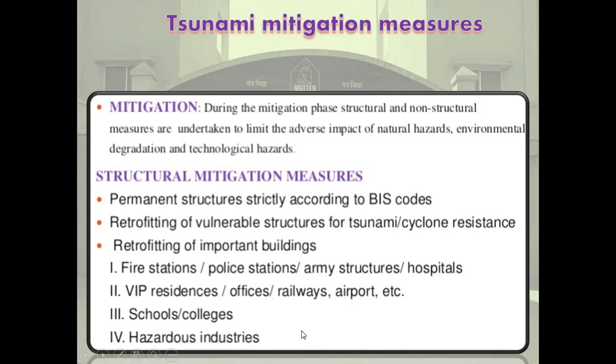Construction of large-scale submerged barriers in water depths of about 6 to 8 meters. Developing sand dunes along the coast with seaweeds, shrubs or trees for stabilization of the sand dunes. Raising the ground level above the designed water level with natural sand so as to protect the entire coastal villages.